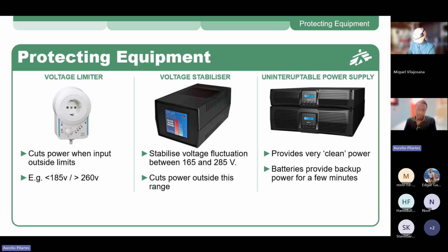However, if you put this AVR upstream of the UPS, there's no inconvenience in doing so, but I would rather use this AVR to protect other equipment that might need this protection more than the UPS, which already has this function. However, there are other things you might want to protect your UPS from, like surges, for example. It's always a good idea to protect your UPS against surges. This is why you should always have one SPD upstream protecting your UPS.